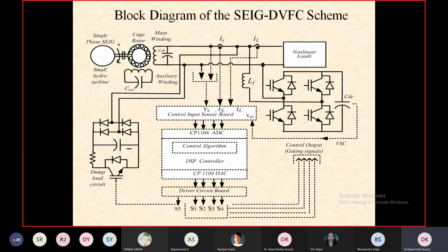Means this VSC will act like a 10 kVAR capacitor. In the very next sampling time, it may act like a 15 kVAR capacitor. Then it will become 20 kVAR capacitor, and then it will become 100 kVAR capacitor. Then it will become 2 kVAR capacitor. Within 40 microseconds, that is equal to the sampling time. In every sampling time, it can change its reactive power value.